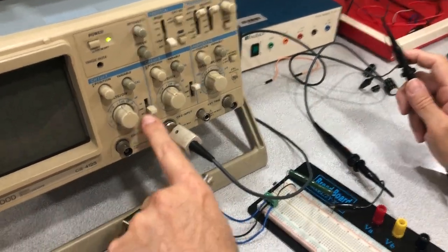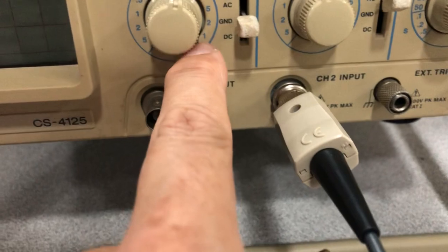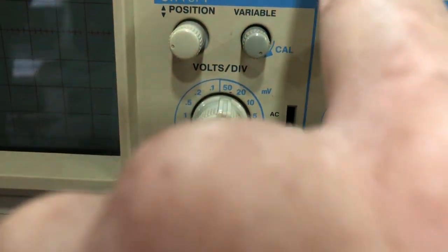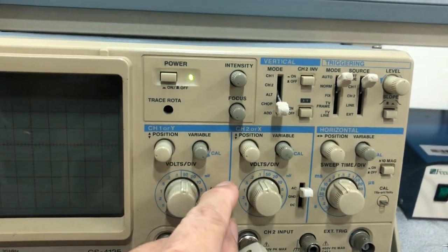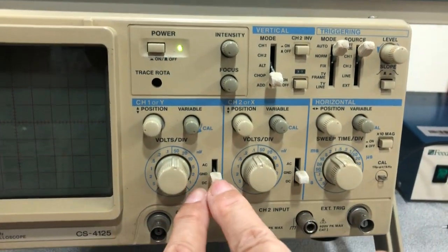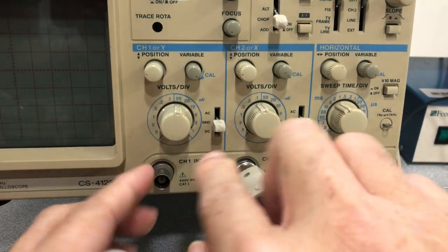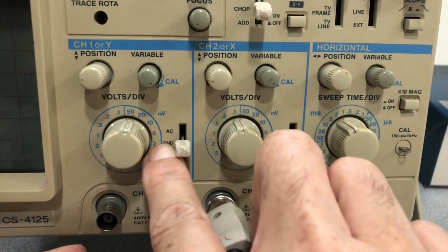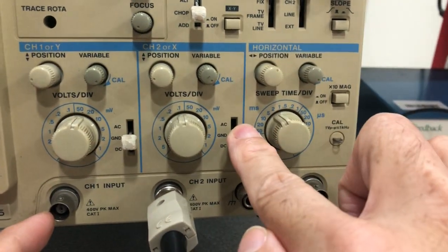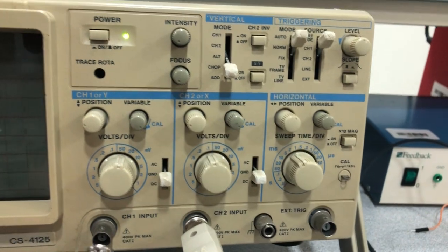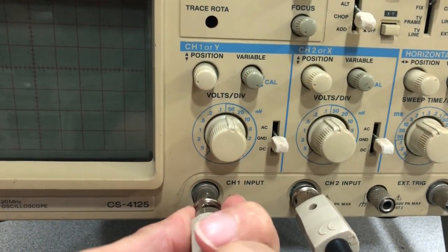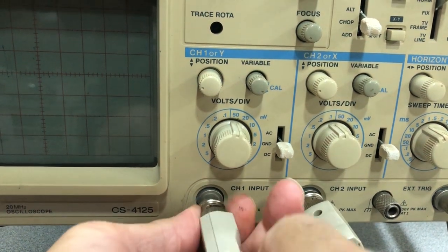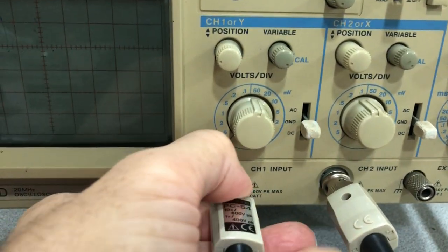If we look at the most important knob, I start with, of course, the intensity. Let me talk about the intensity, but I have to see my beam. So I set the input of the scope to ground, okay? Here and here, so that it doesn't receive any signal from the outside. So I can center my horizontal lines when I show them, okay? But I still don't see where my horizontal lines are for each channel.